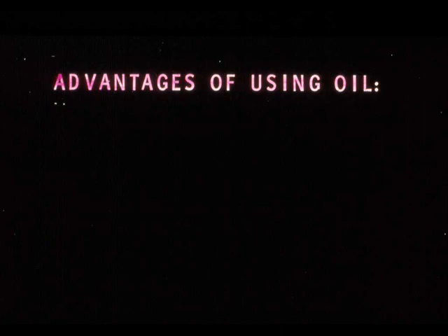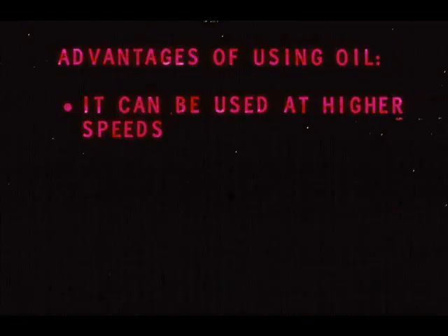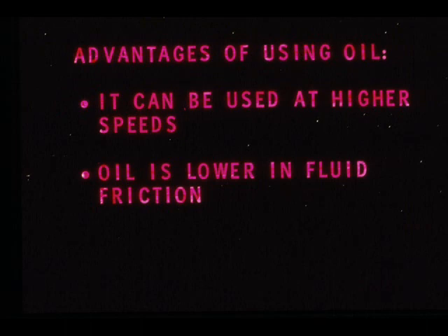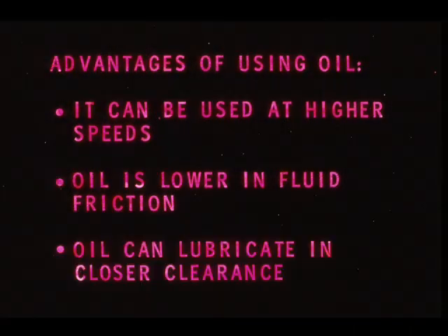Back for a few moments to oil as a lubricant. Oil has these advantages over grease. It can be used at higher speeds for longer periods of time than can grease. Also, oil is lower in fluid friction and imposes less drag on moving parts. Another advantage, oil can lubricate in closer clearances between moving parts than can grease.